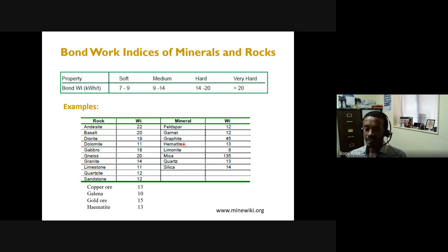So when you have something like this, people use different methods to maximize, for example, the efficiency of grinding. One of the things you can consider is wet milling, so milling in wet conditions. Another thing you can do is reduce the pulp density, okay? And to improve screening, you can use wet screening, because basically you're trying to force particles to pass through the screen rather than doing dry screening. So there are some strategies that you can use to help increase grinding efficiency.